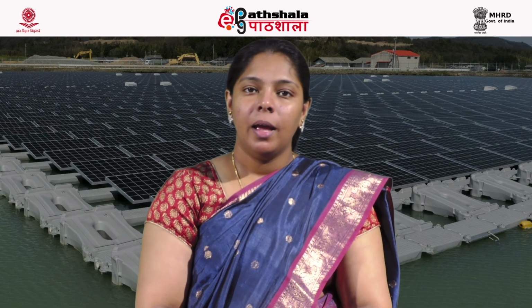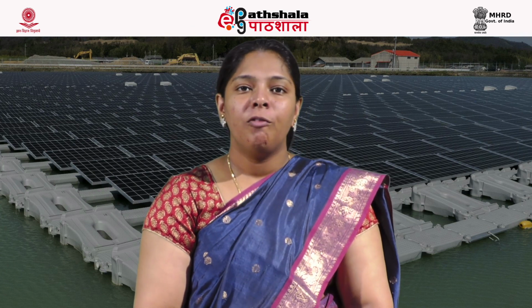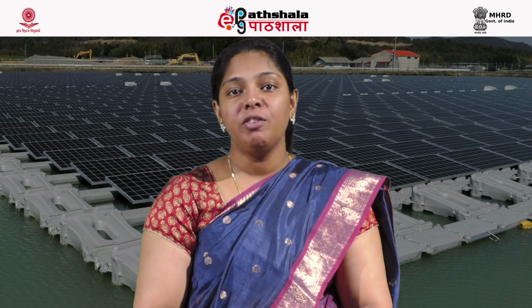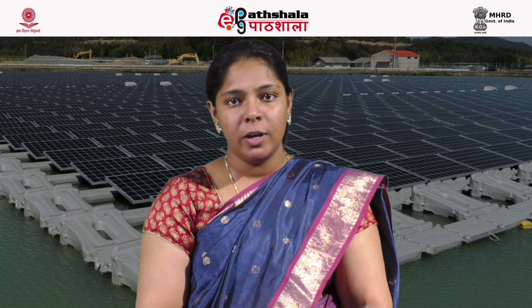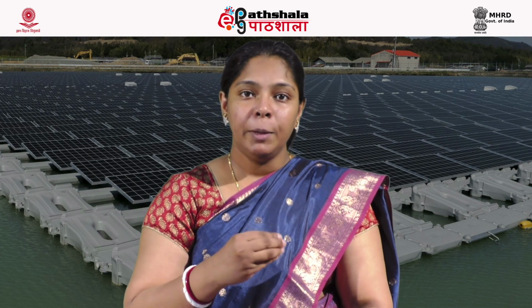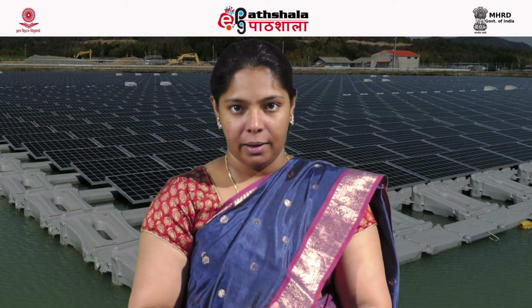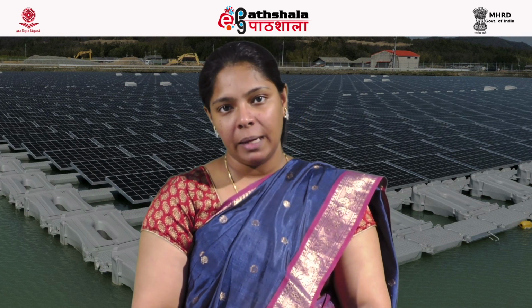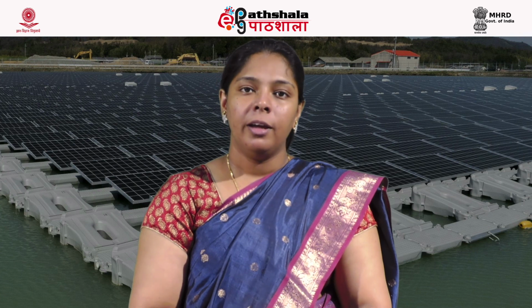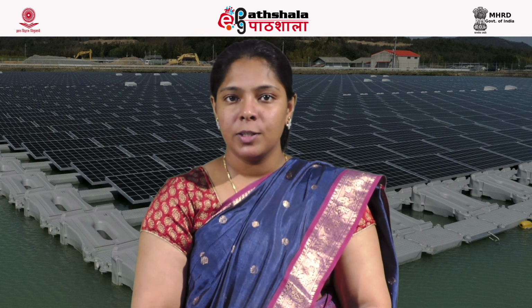So to conclude, in this module we have discussed the solar pond. What is a solar pond? It is an artificially constructed pond. Sometimes a natural pond can also be used for the collection and storage of solar energy. Here, it prevents the convective currents so that the trapped heat is not lost. We have seen different types of solar ponds like non-convecting and convecting. Under non-convecting, there are two types, salt gradient and the membrane type. The most commonly used one is the salt gradient solar pond.